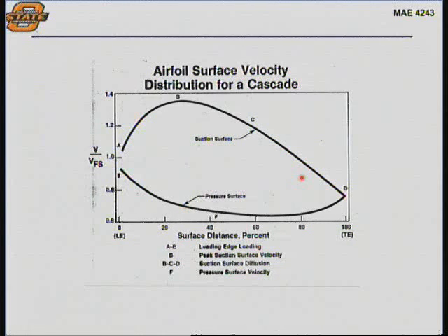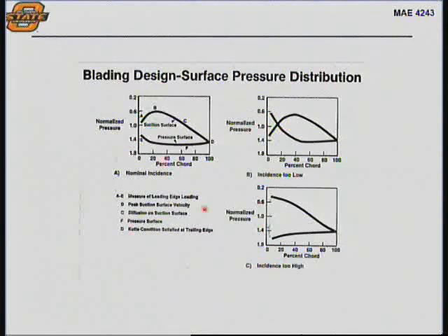Designing the airfoils at a particular radius is done the way that you would look at tailoring a 2D, fixed wing aircraft. But there are differences because of the proximity of the adjacent blades. But essentially, you can tailor the surface velocity and the pressure on the suction side and the pressure side to give you the properties that you're looking for.